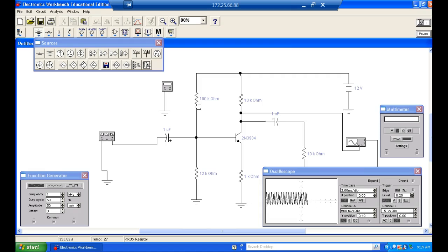That means there's going to be no current flow through this resistor right here except for AC current, guys. So my base bias is going to go to 0. What should that cause to happen? Am I going to lose my output? Well, it all depends on the input. If the input gets above 7/10 of a volt, then the output's going to turn on. But it's definitely going to clip one side, right? So let's open this up and see what's happened.